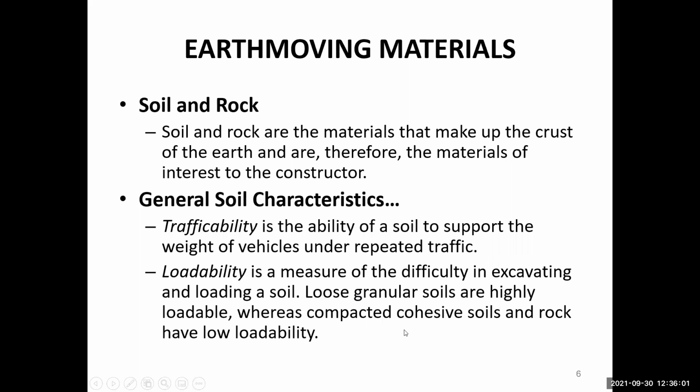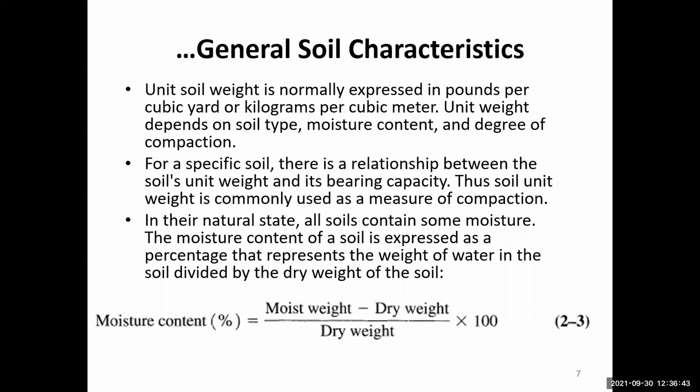Okay, but whereas the compacted cohesive soils and rocks have low loadability. So loose granular soils, it is very easy. That means you will apply the excavator, and that excavator bucket can be filled very easily. But for the compacted cohesive soils, like clay soils, it will need more force and effort of the excavator to excavate it, and the bucket of the excavator may also not be completely filled in one go. So therefore, those types of soils will have low loadability. Okay, trafficability and loadability.